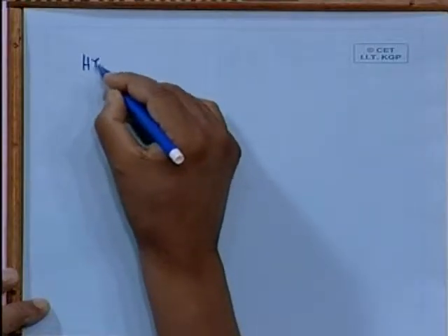We will tell later on that all my calculations depend on finding out a position of the hull when the net force is 0, net moment is 0. That is the only condition. To find that out, I need to find out forces. To find forces, I need to find out integrations. Integrations are all under geometry. This is the most fundamental point of hydrostatics that we must recognize. In fact, I will tell later on about offshore structures, how they proceed, which is slightly different. See, now coming back to the quantities that we require.